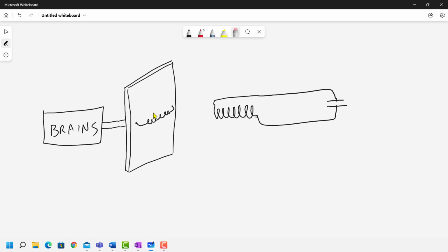Now our next change. We're going to redraw this inductor. Now I mentioned earlier, I don't need to have so many coils. In fact, I can have just one. So what I'm going to do is draw this loop a little differently. I'm going to have it go over and have one coil and come back underneath, and then go back in. So it's not as if this wire is touching itself, but it's just flat against the board and there's a single coil. And in fact, now I'm going to add multiple coils that have the same kind of layout. Now remember, each one is coming out and coming back into the board. I'll just draw a few more.